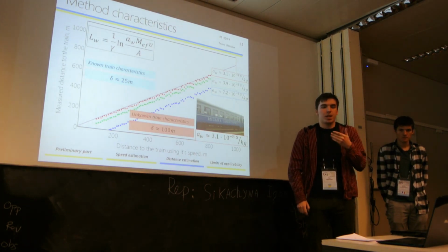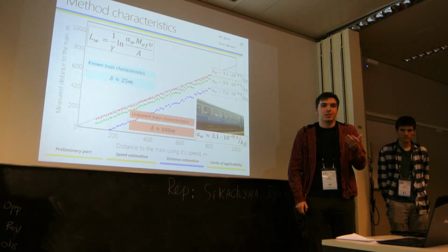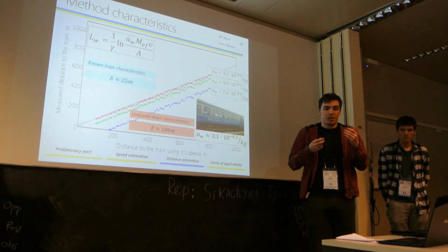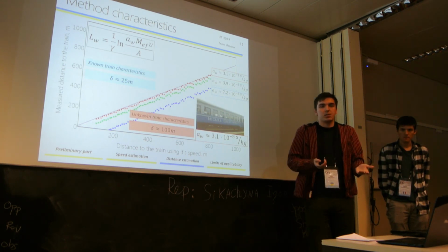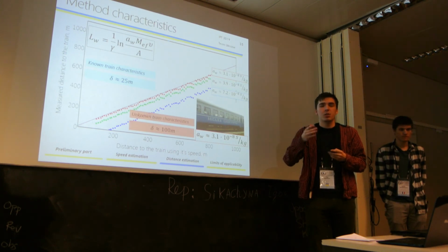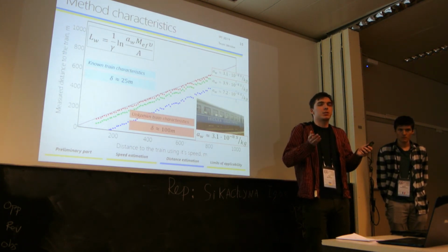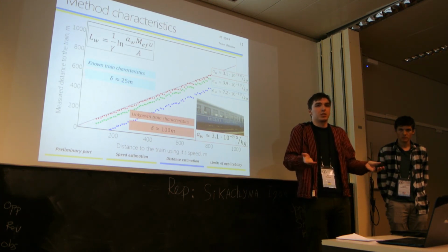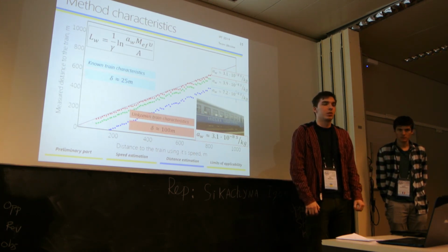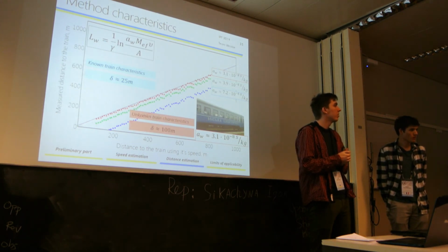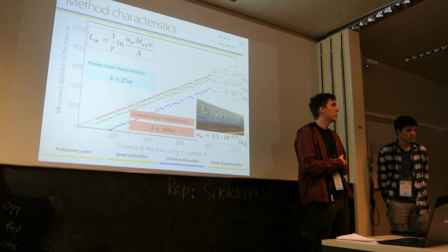Blue tack is the suggested material. A thin blue tack layer helps to attach the sensor. Additionally, yes, it may change the amplitude response and the frequency response, but it didn't really change the results, because we're still obtaining the signal and it still correlated well with the cross-correlation. From our experimental data, we also found that certain types of tape with certain properties work well, such as duct tape, in case you want to try that in future experiments.